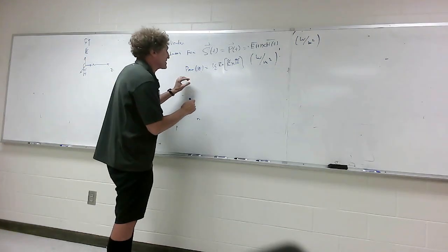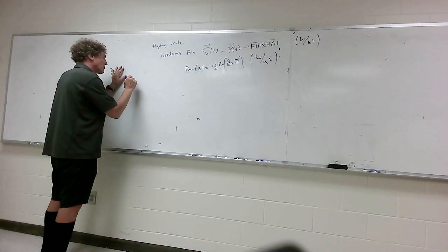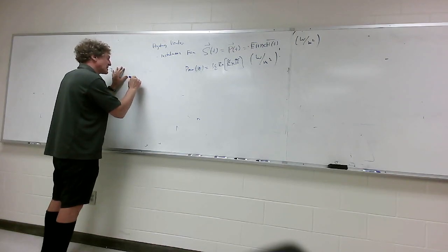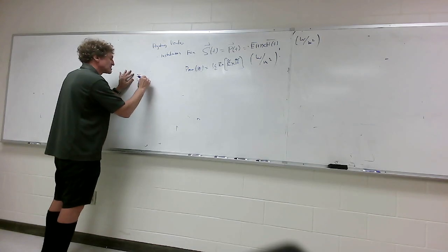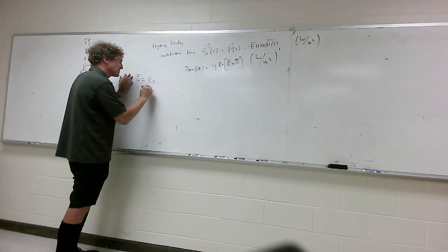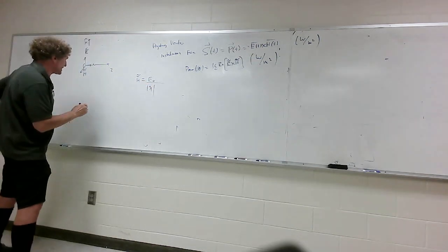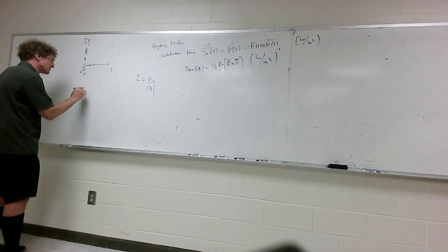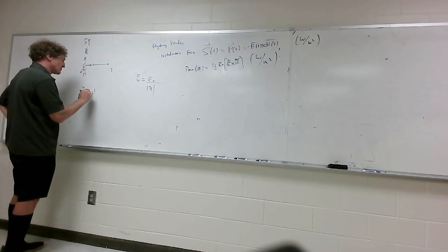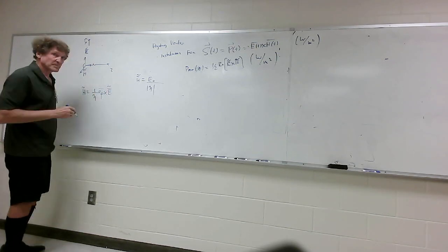If it's a propagating wave, and we talk about E and H, well, I know if I have an E field, I have an H field, right? And the H field for a propagating wave would be equal to E naught over the magnitude of eta. Now, to get H, I could go through the phasor form. I could say it's equal to 1 over eta, unit vector in the direction of propagation crossed into E. Y'all with me on this, class?